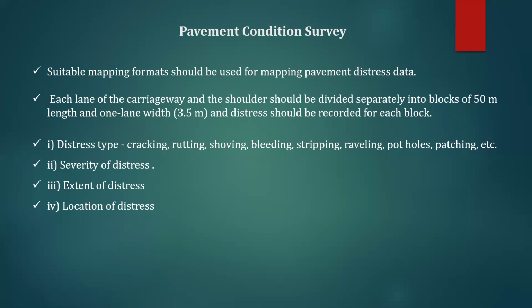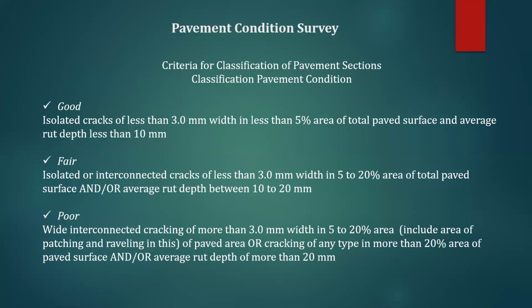So you know the distresses. The distresses are different types, as I mentioned: cracking, rutting, shoving, bleeding, stripping, raveling, pothole, patching, etc. So always you have to understand the severity of distress, extent of distress, location of the distress, everything. Okay. Now, whenever we have decided that we have to go ahead with Falling Weight Deflectometer, that is very much